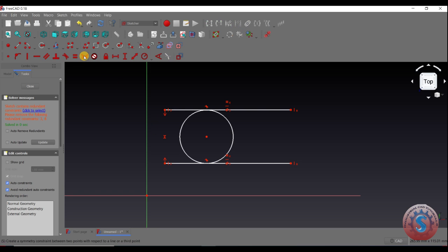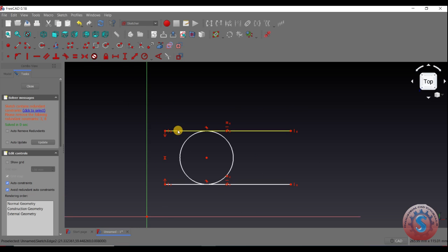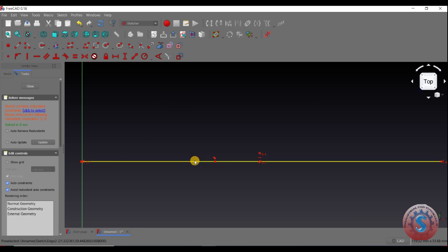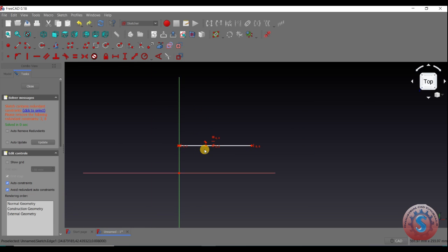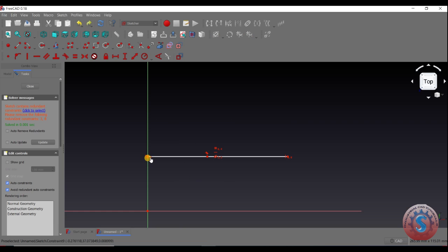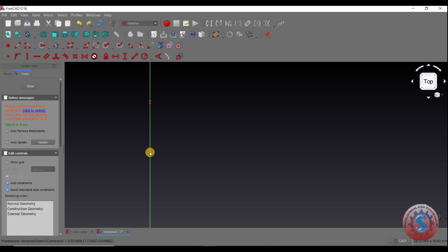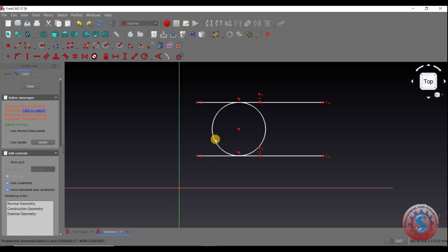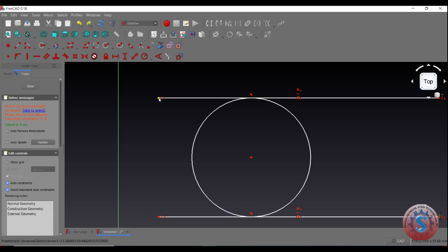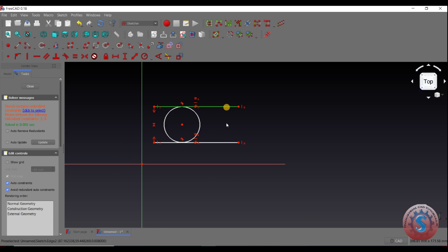And I'm selecting this symmetry. You can observe the symmetry symbol will form, it is moving, see, constraint like this. The symbol is also constrained. If you click on this constraint, it is merging. You can observe that is called a symmetry constraint. I'm selecting the first and second and selecting the symmetry option. Like this you can give any of the constraint properties.